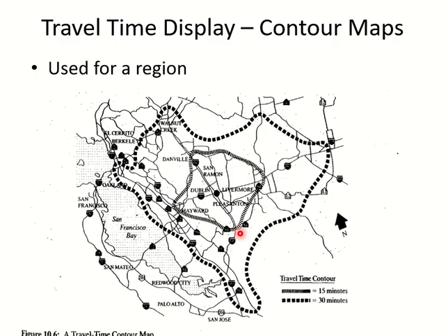So now you can see that doing a travel time study on one highway is not enough to produce this map. You have to do it in the entire region. So you have to go from the benchmark in all directions of the region so that you can make this travel time contour map. Okay, why do we make this map? This map shows us, if you are going to build a new facility for the public, then the travel time contour map tells you from which areas people are more expected to come towards this facility, because people take decisions on the basis of travel time,